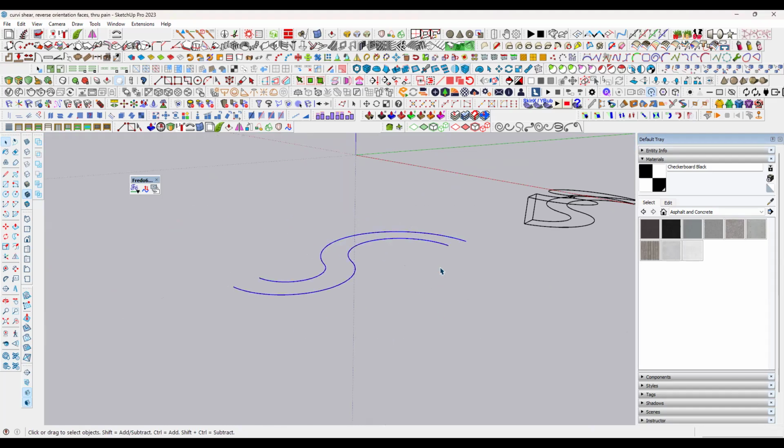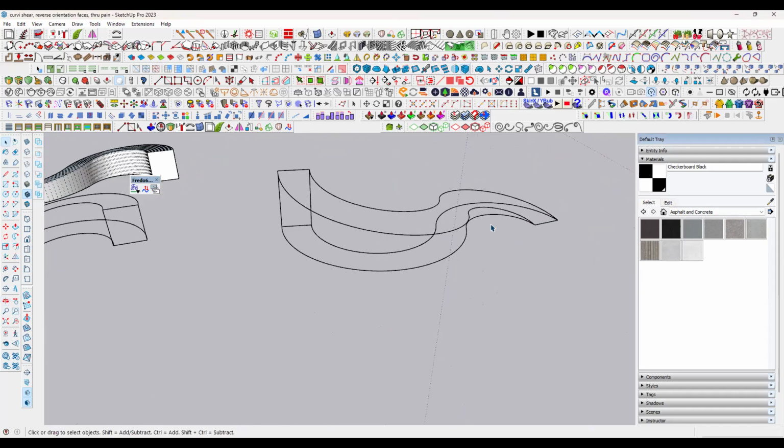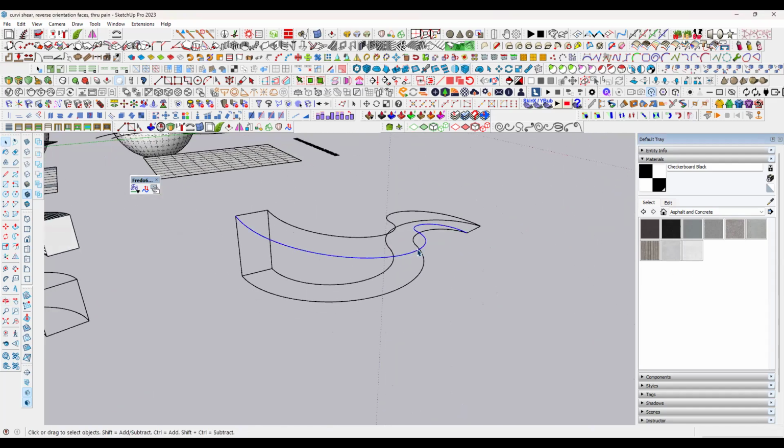But sometimes I want to reverse that. Instead of creating this side, I want to create the other side. So now click this one. Here we have an option, reverse curve orientation. Click and click OK. Now see, this side you are getting a curve. And then finally, I want to apply the surface. How can we create a surface on this?